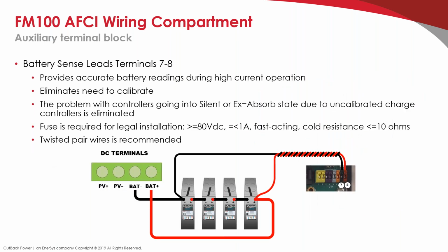Moving on to pins 7 and 8, so the red and black pins all the way on the right side. These are the battery sense terminals, one of OutBack's features for a long time now. An important feature, especially for an advanced charge controller like this with very fast sweep and very responsive MPPT algorithm. That battery sense terminal is important